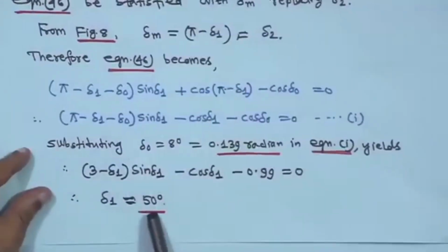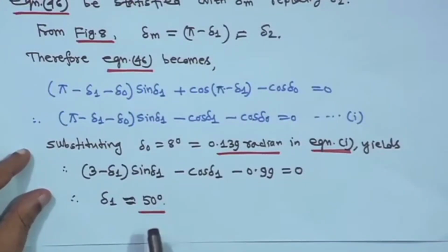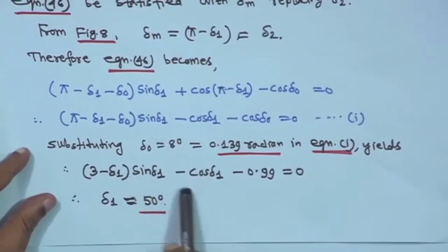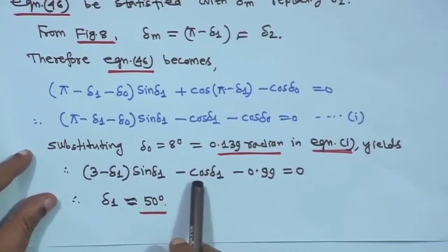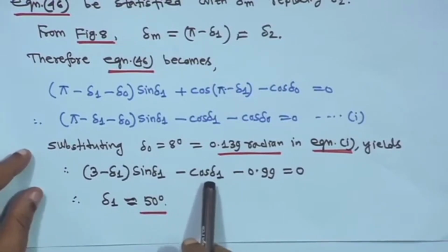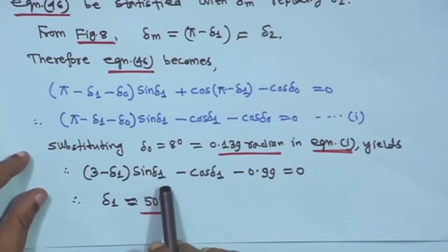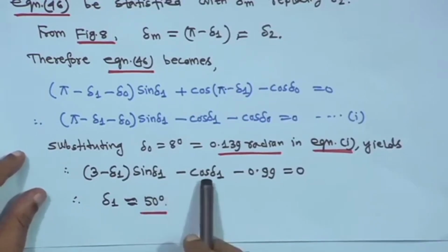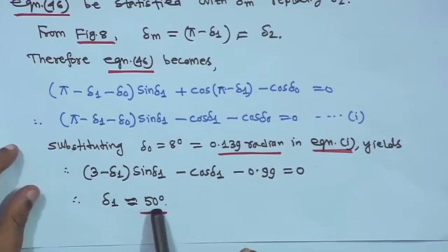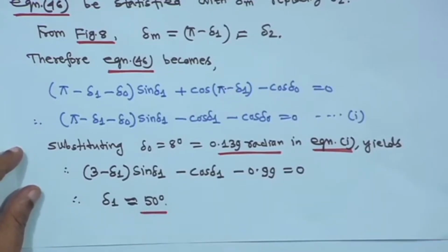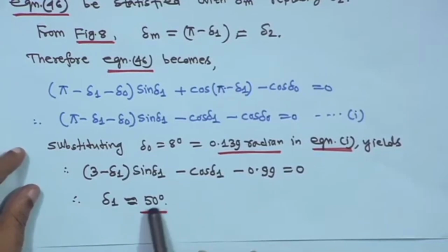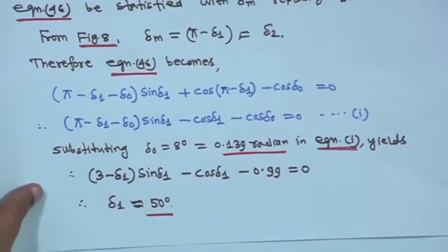Okay. So, let us come back to the power system stability. Actually, in the previous example, when I was telling that delta 1 is 50 degree, I forgot to mention one thing, that this is a non-linear equation and one has to solve iteratively, but for the classroom purpose you have to try a little bit of trial and error, and that is why delta 1 is approximately 50 degree. So, this I missed, I forgot to tell you. So, this is a non-linear equation, right.